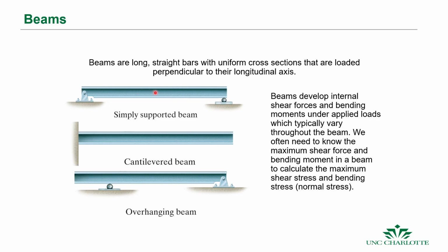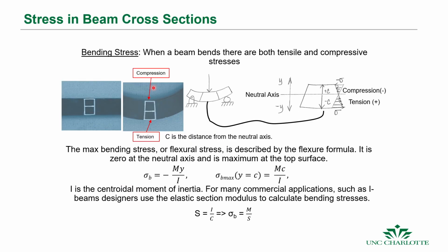so we can calculate the bending stresses. Okay, so we've spent some time on calculating the load, shear, and moment diagrams as a function of the distance in the last homeworks. So in this case, we want to find where that max moment is, and then we can find out what the bending stress is using the flexural formula.